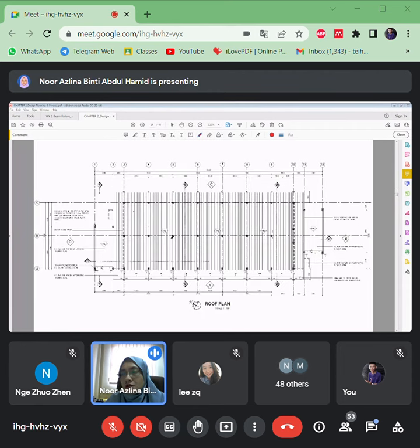So this is the roof plan. The architect will show all the arrangements of the roof systems. So here we don't see very clearly what size, okay, for the trusses, members, materials, and what roof system will be used: metal deck, zinc, or open space, just a transparent fiber and so on. So all this should be in your roof plans. Okay, all the information.